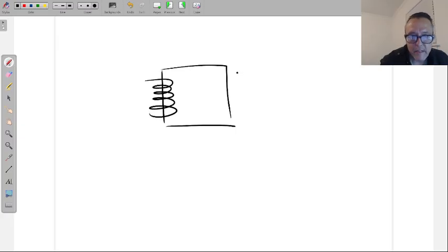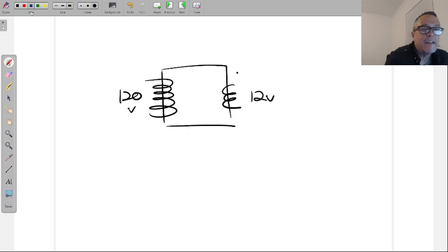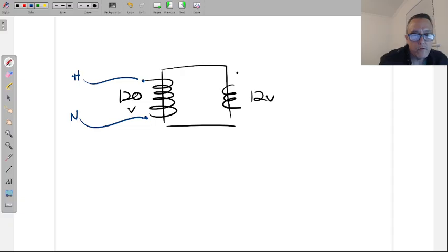The doorbell one is 1 voltage in and 1 voltage out. Not just doorbells, you can use this anytime you need 12 volts. But you can only connect this transformer to 120 volts on the primary side, as we said yesterday, hot and neutral.